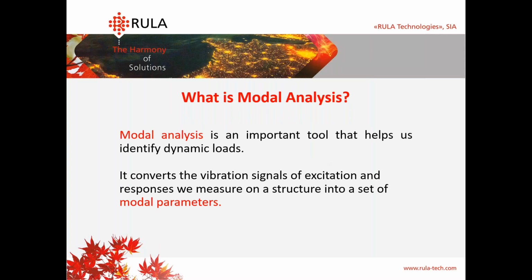So what is modal analysis? All systems have operation conditions that cause them to respond to certain excitations. The loads can be either static, like for example a beam on which a mass is placed, or dynamic, like a beam vibrating under some external force. Dynamic loads are the concept we need to pay close attention to. They may cause responses that are unacceptable, and we can call them resonances. Our goal here is to find a way to minimize or eliminate this undesired response.